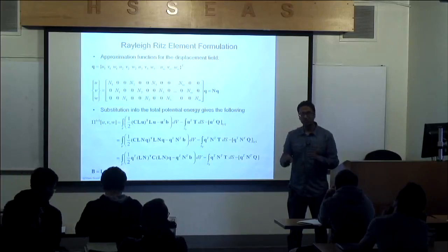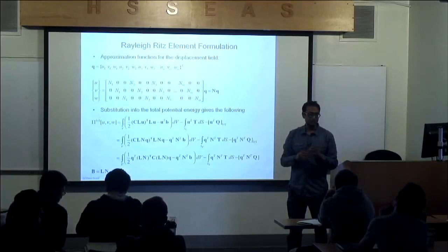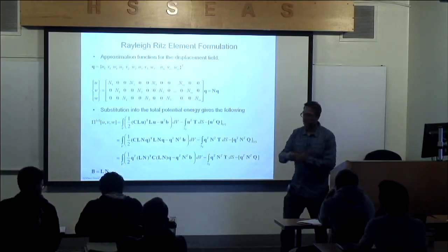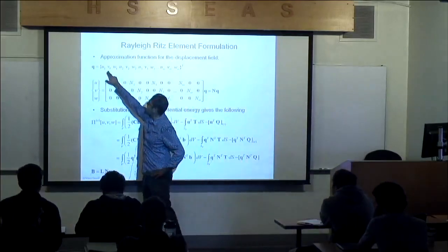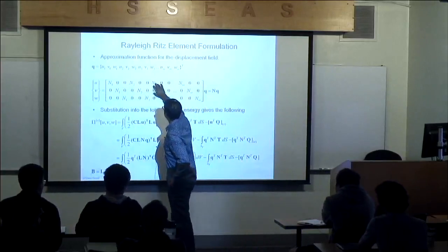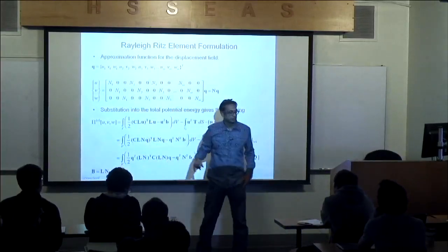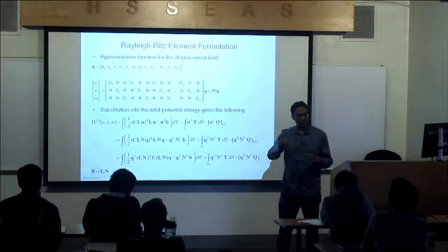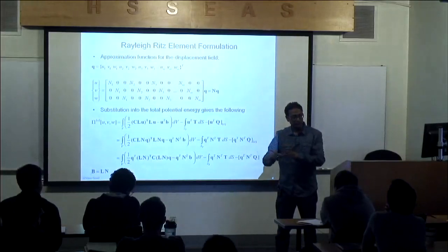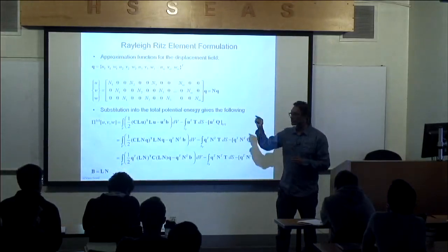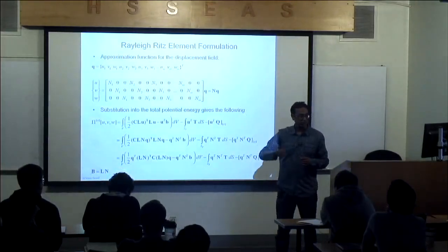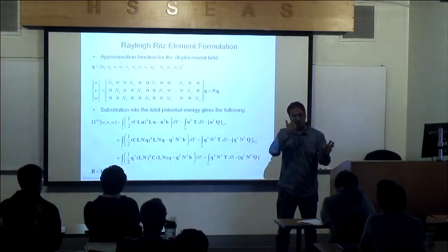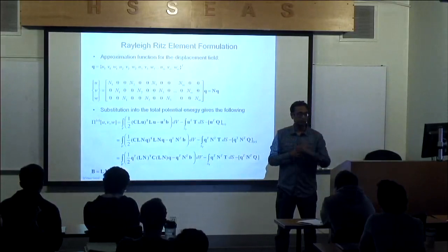These shape functions constituted the basis functions, and in essence what you have there is an approximation function. Isn't U equals N1 times U1 plus N2 times U2 basically an approximation function? Just like Rayleigh-Ritz, you have U equals phi times unknown coefficients. Now your unknown coefficients are the unknown nodal quantities U1, U2, U3, U4, and your shape functions become the basis functions in weak form Galerkin or Rayleigh-Ritz.